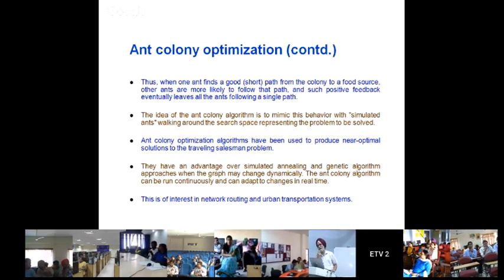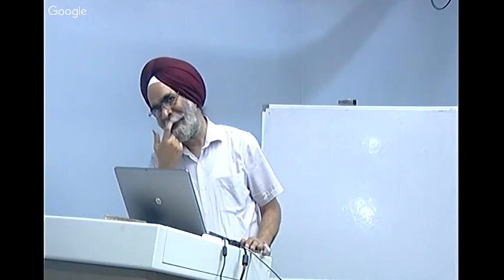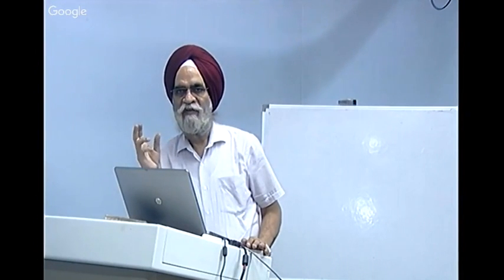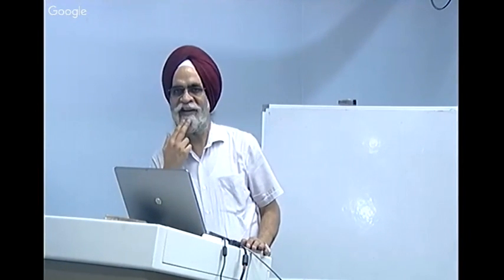Similarly, I have put a constraint on F, the feed rate. Depending upon the material I have to cut, the cutting tool material, the machine availability, what machine I will be using and what is the capability of the machine, what can be the maximum and minimum feed available on the machine. Let's say the maximum feed available on the machine may be very high, but the recommended value for a particular cutting tool and work material may be limited. I can put a limit on that. So I can make constraints for this.